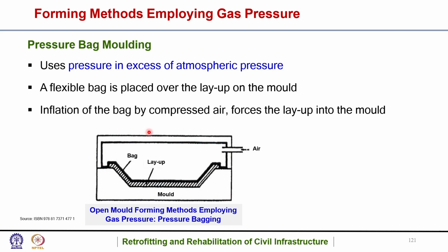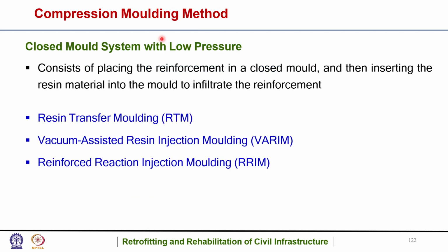Like, the bag is inflated by the compressed air and it forces the layup into the mold. So open mold forming methods employing gas pressure, that is pressure bagging. Then there is closed mold system with low pressure.